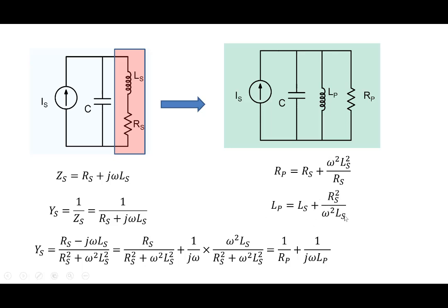Right, so now the zero power factor frequency, or zero phase difference frequency, or unity power factor frequency, would be the place where the reactance due to capacitance will cancel the reactance due to the inductance that is there. Okay, so that would be easy to calculate here once you do this kind of a transformation.